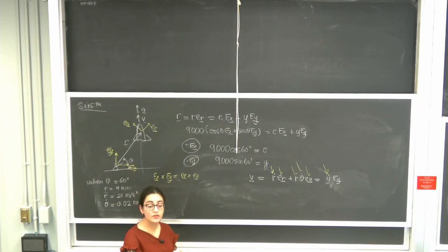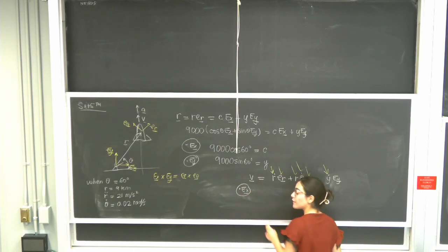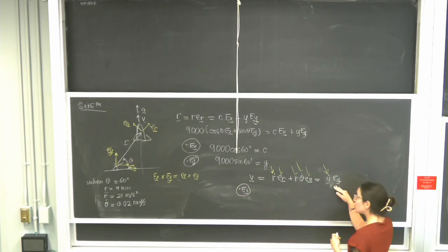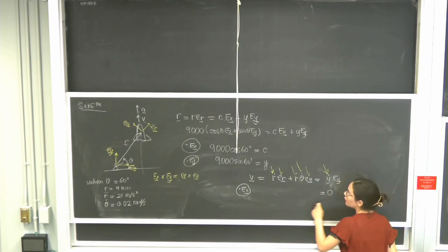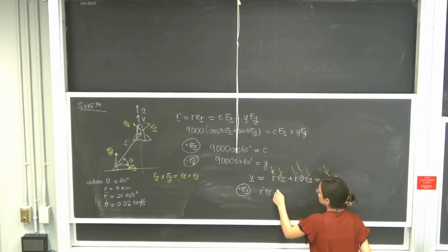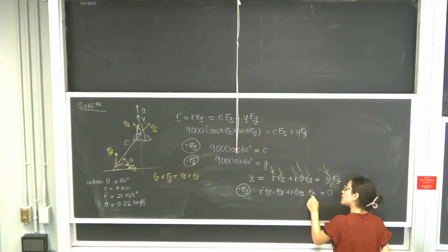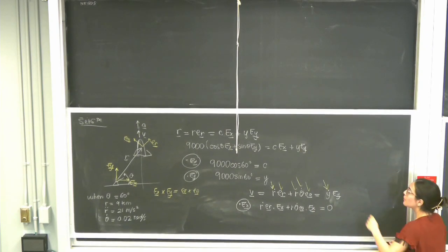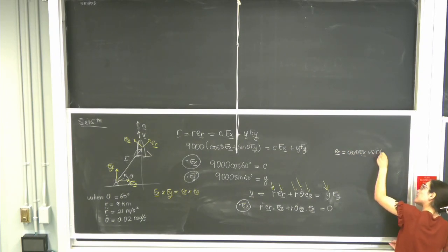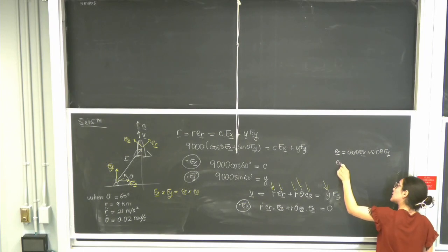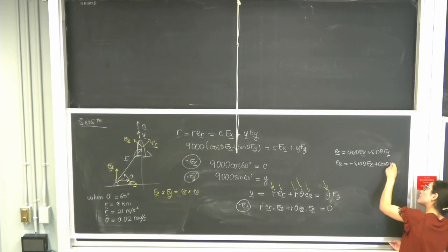So let us see. Your friend is suggesting, let me project this equation along EX. If I project along EX, will this term go away? Yeah, because I'll have y dot EX, so that's going to be equal to 0. Now what about the other ones? I'll have R dot ER dot EX plus R theta dot E theta dot EX. Interesting. So remember ER is cosine theta EX plus sine theta EY. And E theta is minus sine theta EX plus cosine theta EY.